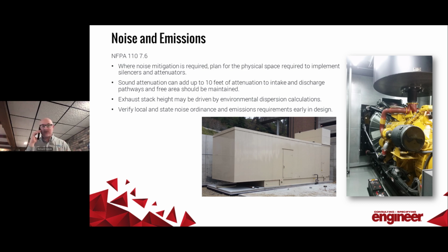But remember, it's not just the noise ordinance to the neighboring properties. It might be FGI compliance with noise into, say, patient rooms or occupied spaces in the building. So we want to take that into consideration because even NFPA 110, 7.6 says, be aware of noise.